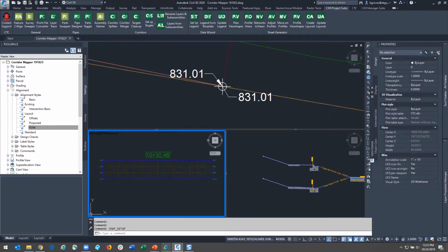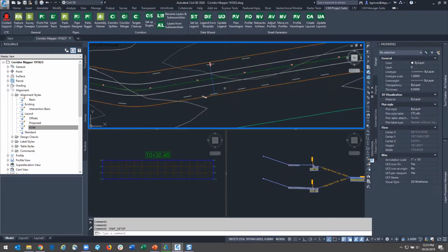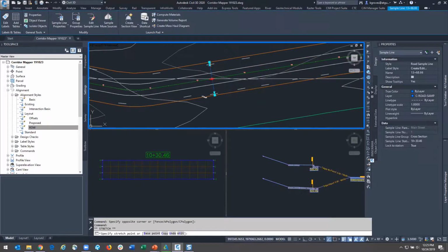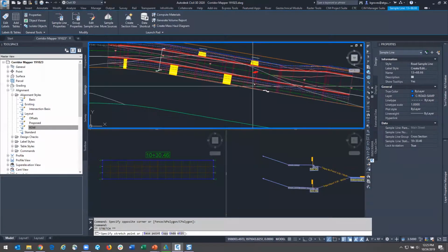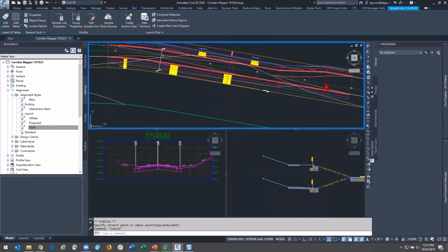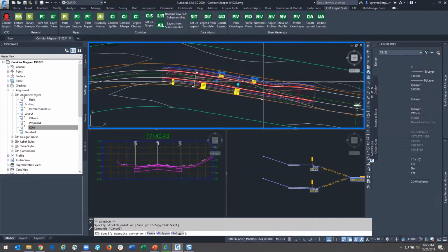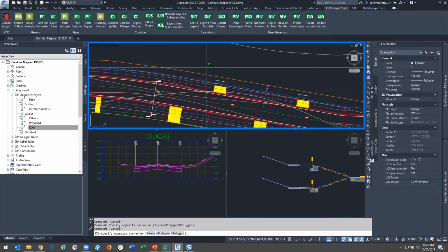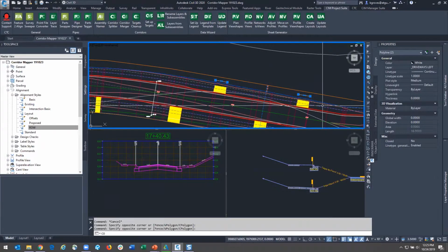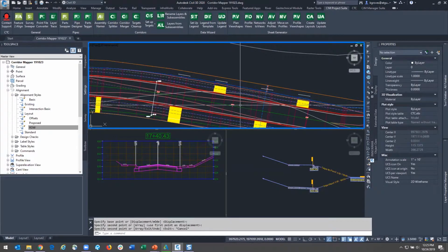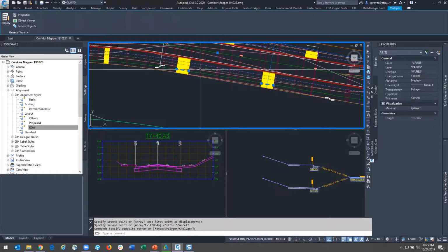So going through in my corridor, I've been able to not only set up all of the things that I normally would have to do, horizontal and vertical targeting for lanes, right-of-way tie-ins, or what have we, but now that I've got the rest of that stuff set up, it's all out of the box no matter what, I can come in here and I can take my conditional subassemblies and their targets, and I'll add 2 over there, and there's 2 hiding in here somewhere.